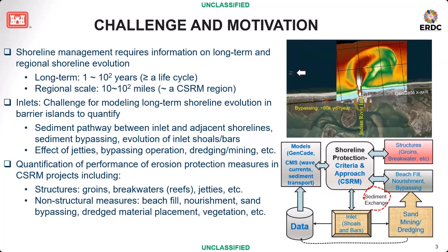We mostly have coastal storm risk management projects. If you consider Barrier Island coastal erosion protection, it is about 10 miles, several tens of miles, that kind of scale. We mentioned before the capability of inlet bypassing. We have some empirical methods to simulate this sediment pathway, but it is still challenging to provide more accurate prediction of long-term morphology change. That's really difficult, but from practical simulations we have a good handle on sediment bypassing across inlets.